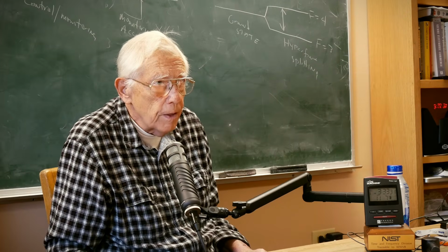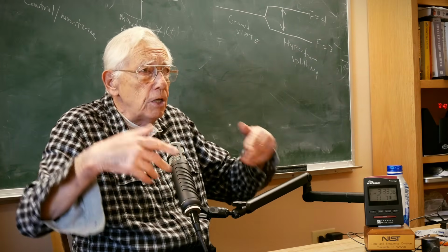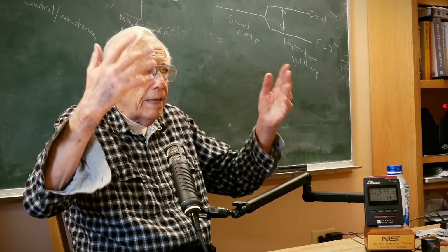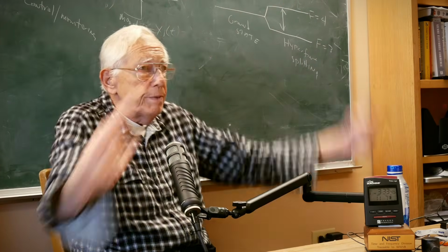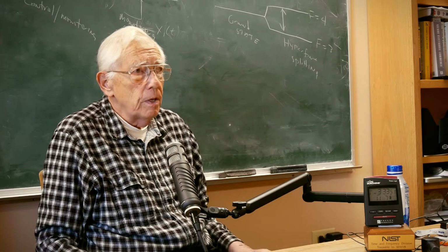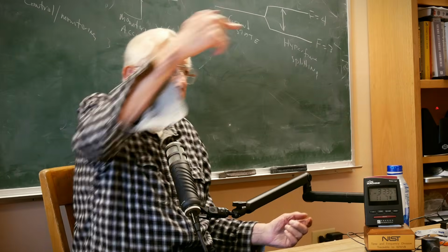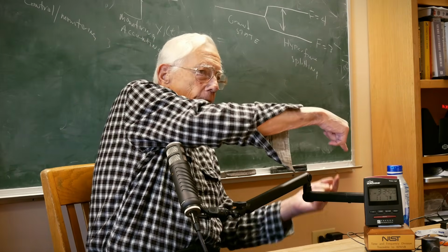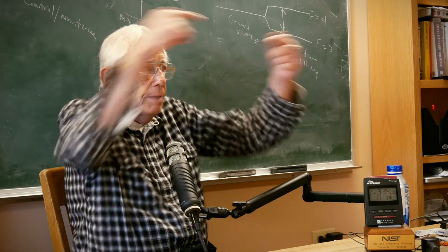Now, the GPS system uses a combination of all of these methods. The GPS system broadcasts the properties of the atmosphere or the ionosphere, so you can calculate the delay. It uses the common view method, so you receive the signal from one transmitter in 2 places. It doesn't use two-way, but the two-way method exists. The two-way method is used with passive satellites, where you send a signal from here up to a satellite, and the satellite echoes it down, and then the other signal goes back up the other way. That's a standard method, and that depends on the symmetry of the path in 2 directions.